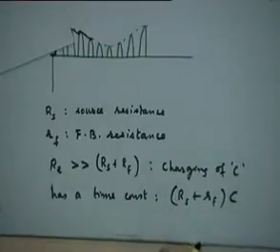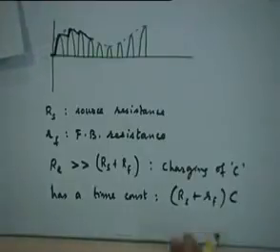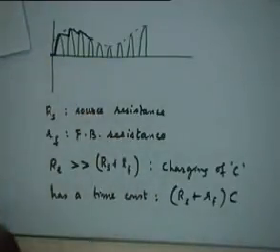Can we quantify this, how small it should be? It should be much smaller than, let's say, the half cycle duration, or the cycle duration of the carrier wave, so that it follows the carrier as it comes, more or less.